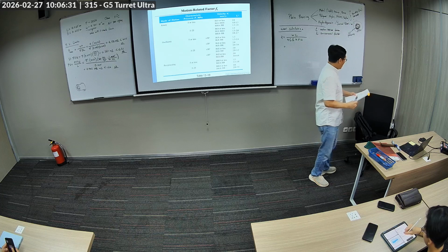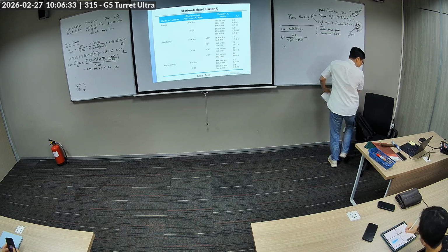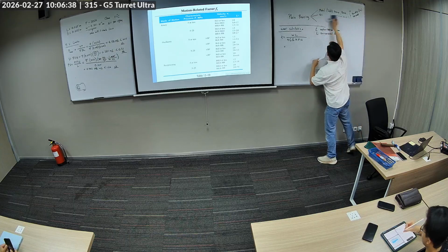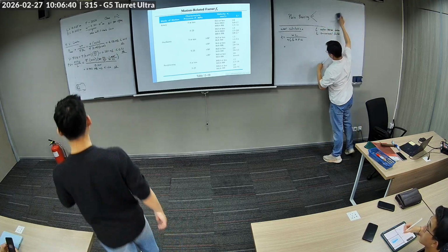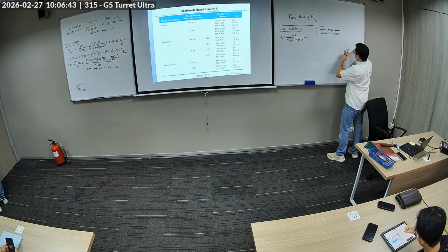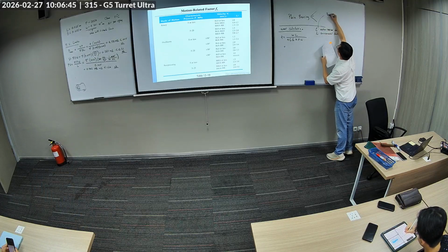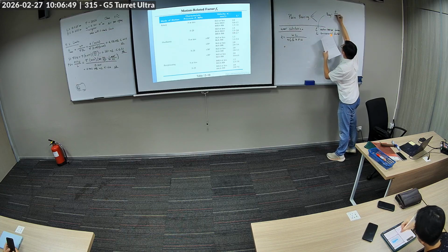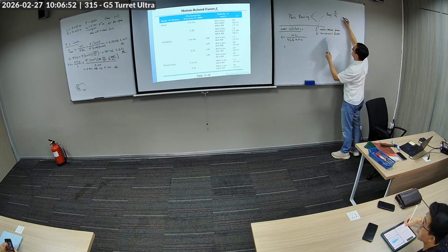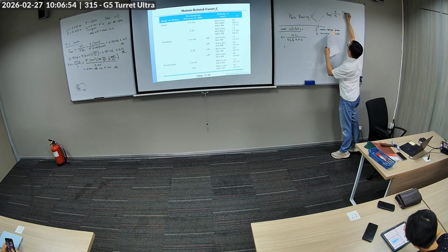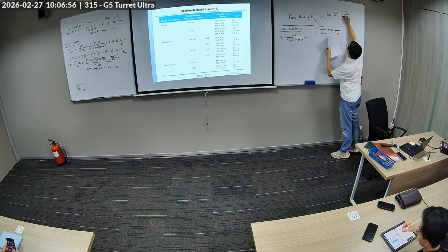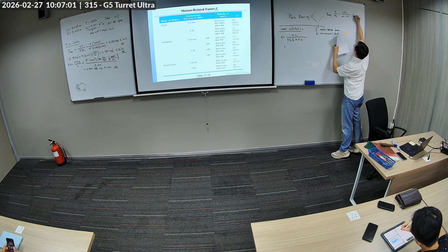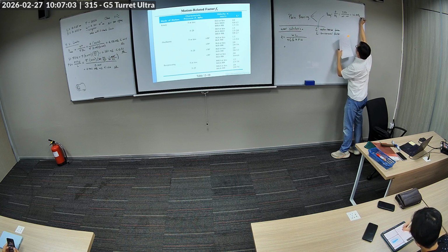Okay? So in order to determine F1, we're going to have to do a quick calculation. I'll just erase this. So in order to do F1, we need average pressure. And the average pressure formula is F divided by dl. Not the maximum pressure, this is the average pressure. It's 2250 divided by 0.025, 0.025, 3.6 megapascal. Okay?